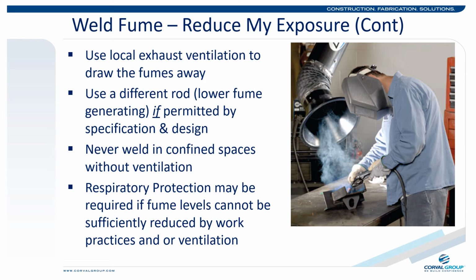In the event that work practices and ventilation are not sufficient to reduce exposure to acceptable levels, respiratory protection may be required. Should respirators be necessary, all workers that wear a respirator must be medically cleared to do so, have respiratory training provided, and be fit tested for the respirator that they will be wearing.